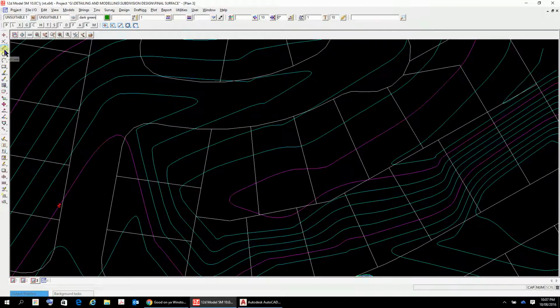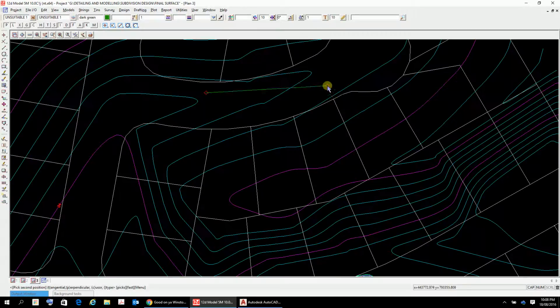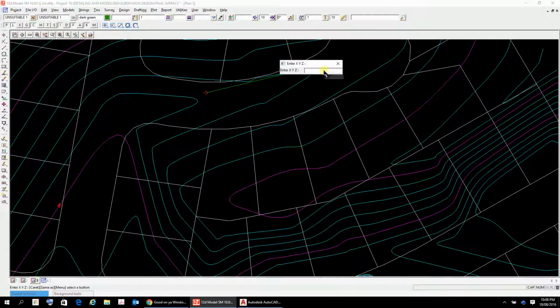So I'm going to draw a line here. Just draw a CAD line there. Just put a point there. Accept. And sort of out there is going to be about 90 meters. I'll try 80 meters. So push the space bar, BD, to tell it that I'm going to do bearings and distances. Again, I'll put it at 80 degrees.